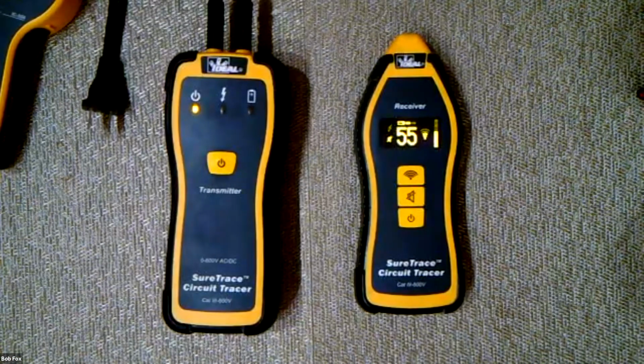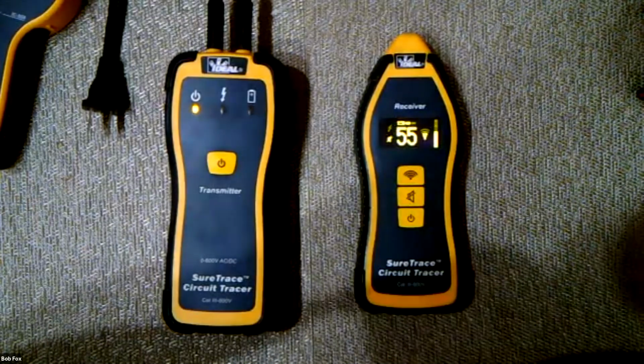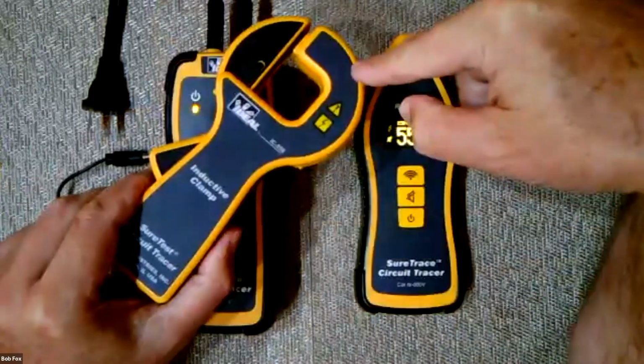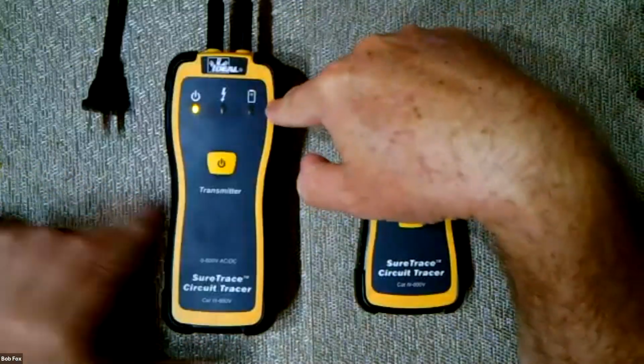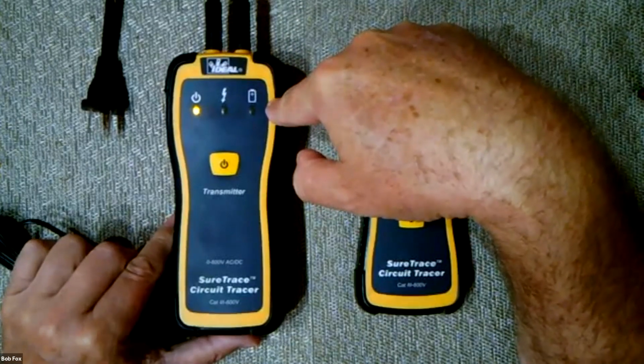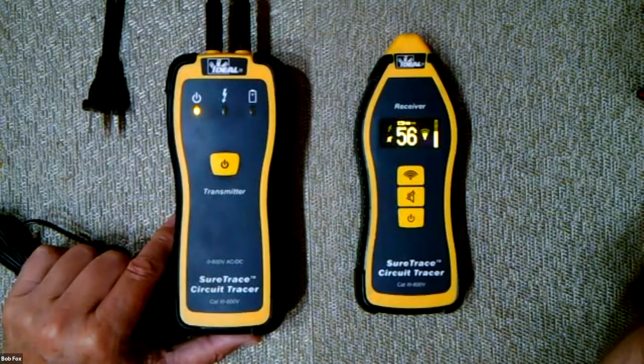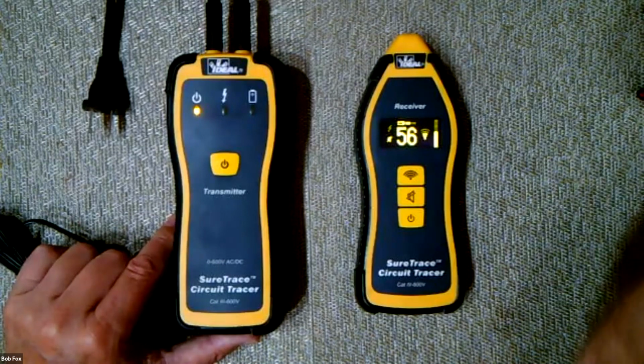We have one other question. What distance can the inducer function in underground tracing? Now, when you say inducer, to me, this is the inductive clamp. You probably mean the transmitter. If that's the case, you can't take this to the bank, but I've had one report where they were picking up the signal 4,000 feet away. This was on a golf course, and I believe it was control circuits for sprinklers. Having said that, hundreds of feet easily on an energized and closed loop.